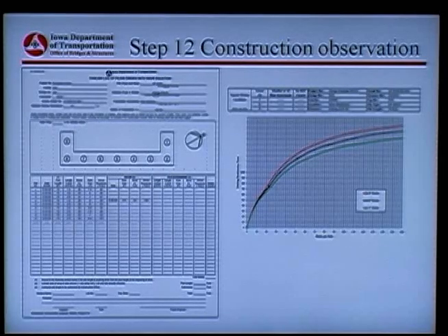The plan length is here. The length cutoff. In other words, it's not uncommon to see that the piles get driven down a little differently, and so we record how much we actually cut off. What the blows per foot was when we finished up. What the stroke was. In this case, it was like 7.5 feet here on that pile. And then what the driving resistance is, this is the value being plucked off this bearing graph here.